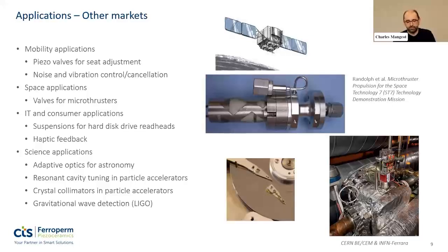We have micro thrusters powered by piezo actuators. This is an example here with a piezo stack that is embedded into a device here, and that opens a small valve. And by controlling exactly the amount of gas that is released through this valve, you can adjust the position of a satellite.